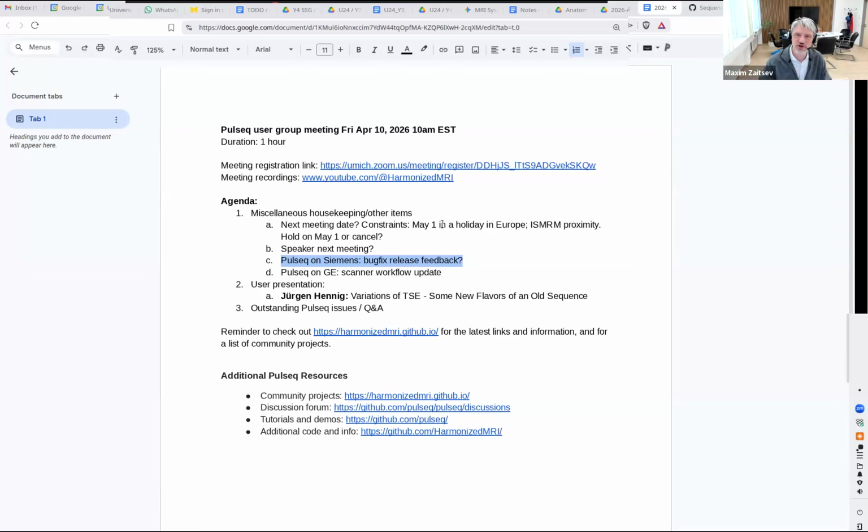So you cannot use very, very high gradient strengths for the readout, because the cutoff of the analog filter will already kill your signal at the periphery of the field of view, and the analog filter will induce phase errors. You will have a modulation of the intensity, which is due to the Q factor, the resonance property of your receiver coils, because it's typically not extremely high.